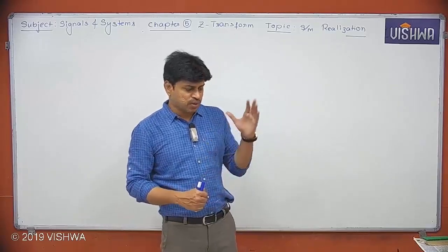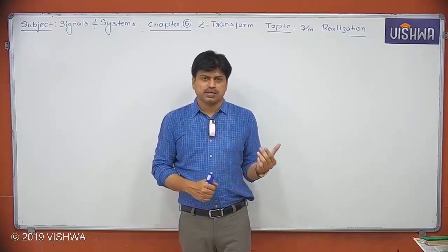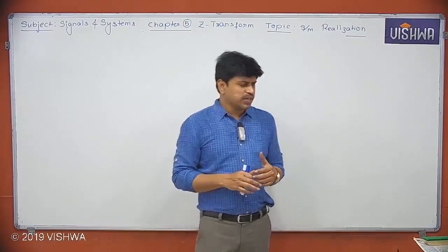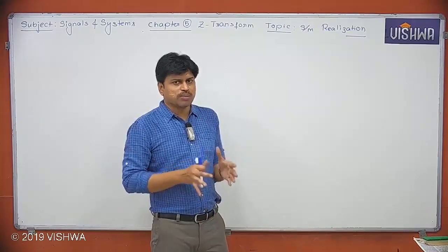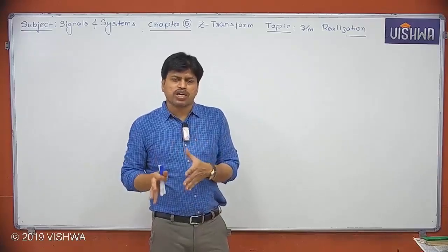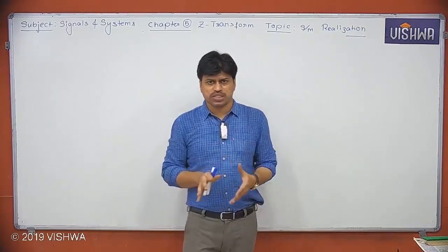In continuous time we used the Laplace transform, so here we are going to use the Z-Transform to construct a system. Construction means we don't have to worry much. We simply have to see what the block diagram representation is for a given transfer function, and if a block diagram is given to you, how to convert that into a transfer function. These are the things we have to see now.